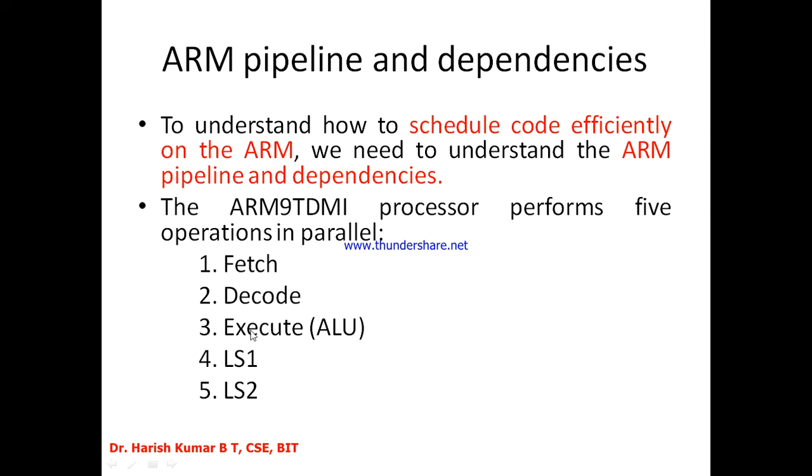And for load and store, execute computes the address. This is what you have got to remember: address is not the result or the answer. For all data processing instructions, this computes the result. For load, store and branch instructions, this computes the address.